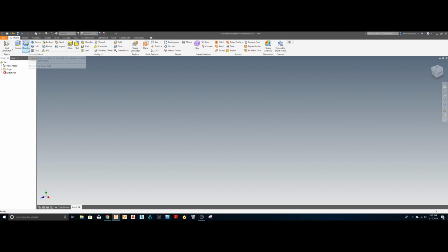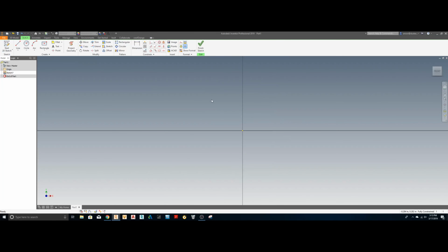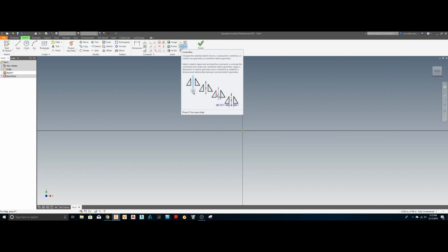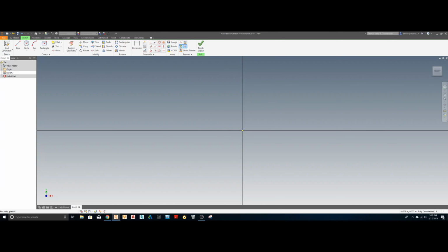And now we'll move on to the revolve command. As you can see from the picture, there you create half of it and it will revolve the entire thing after you've created it. So again, let's do a sketch on the XY plane, and we'll start with a center line. These are your different formats.